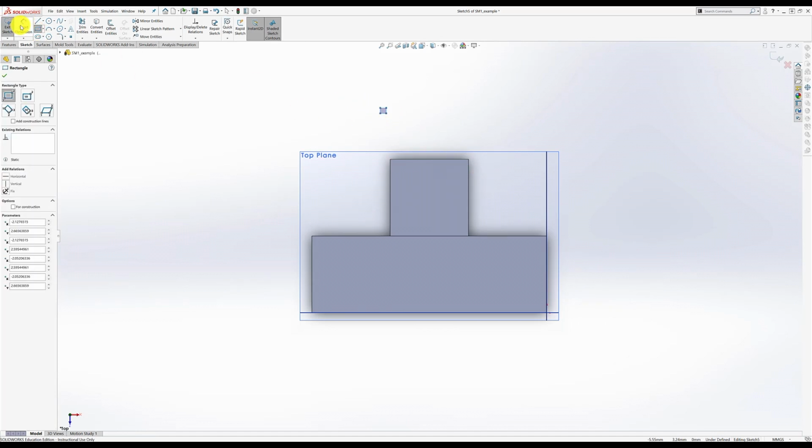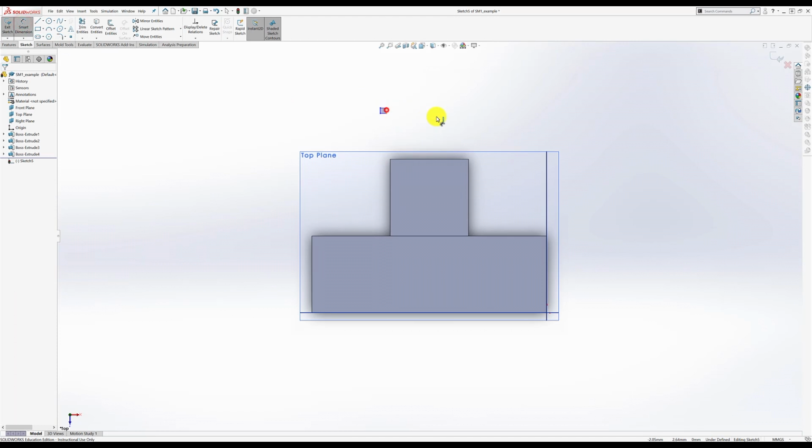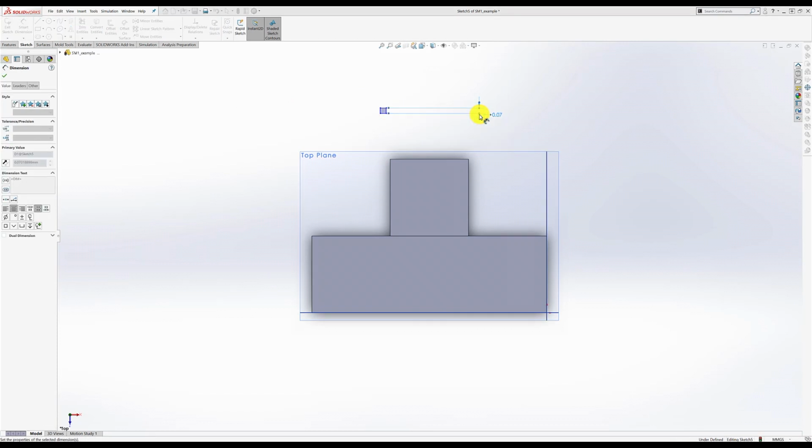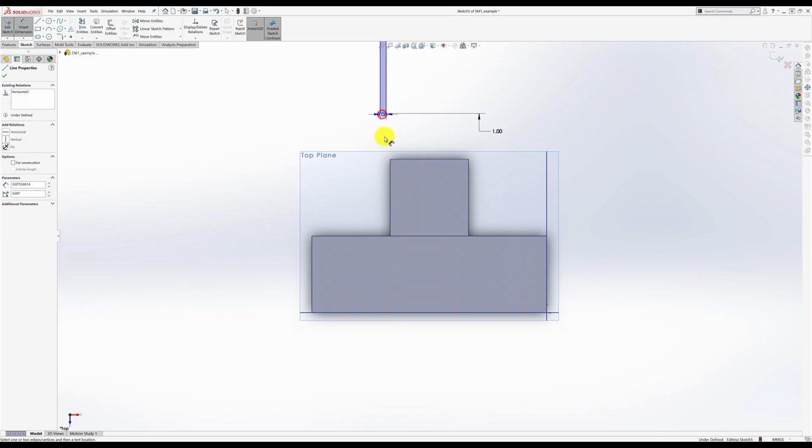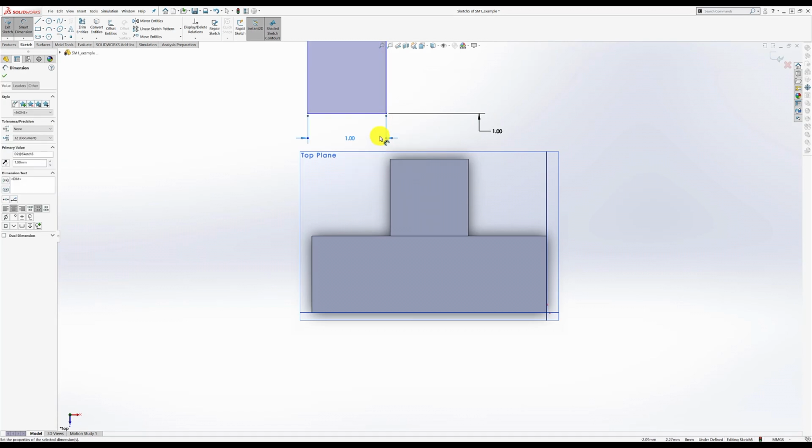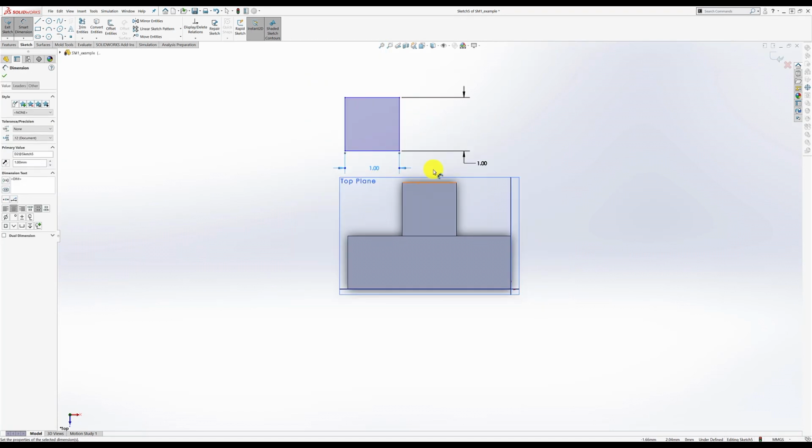Okay, I guess I could do that. That was a little bit of an accident to make it that small, but no big deal. I can just fix it by doing this. Now I got my size the way I want it to. I need to place it in space. Now I can place it relative to these other features, but the bottom line is that I want to place it relative to things that I know are not going to change in the model.